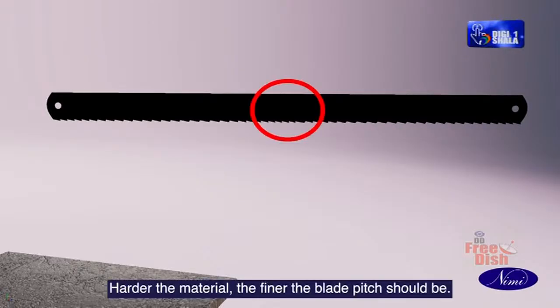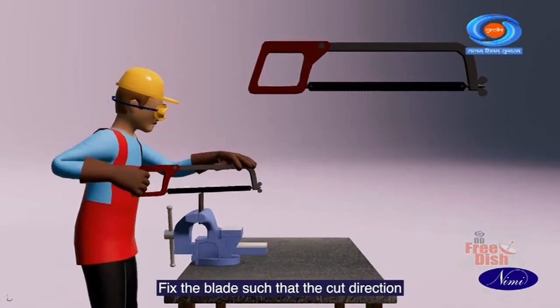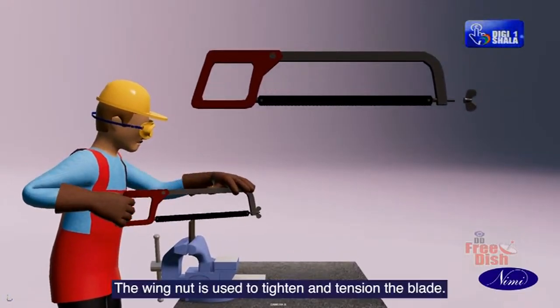The harder the material, the finer the blade pitch should be. Fix the blade such that the cut direction is towards the teeth. The wing nut is used to tighten and tension the blade.